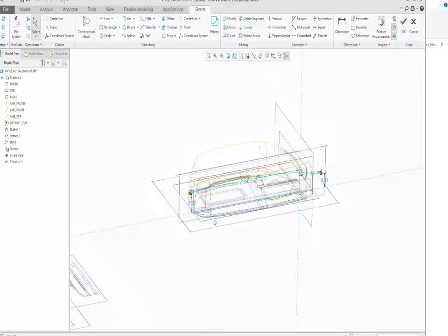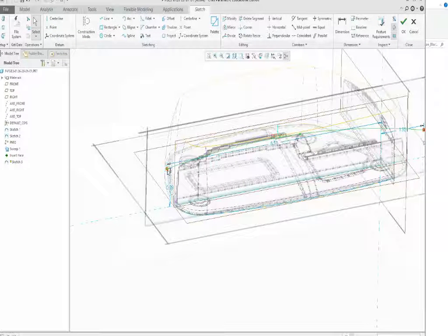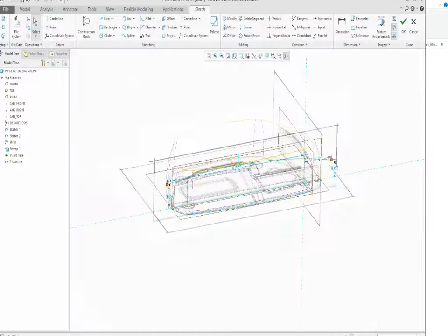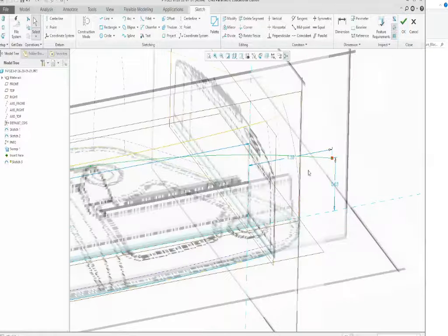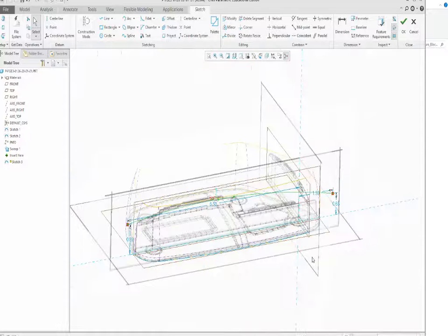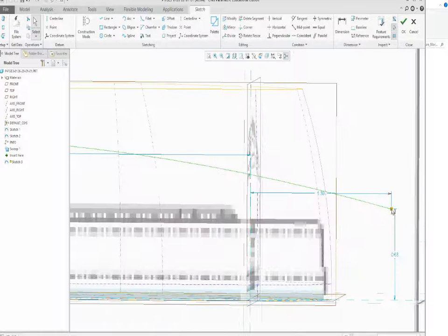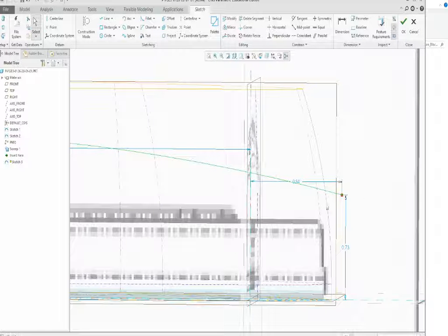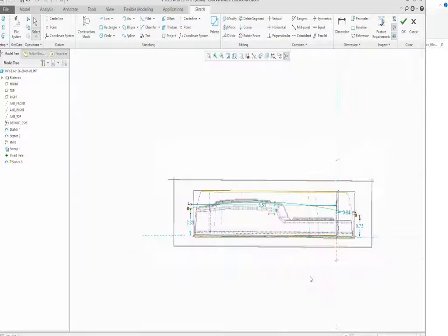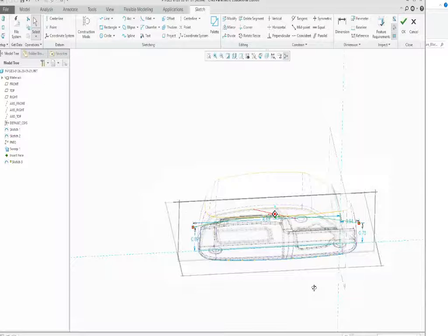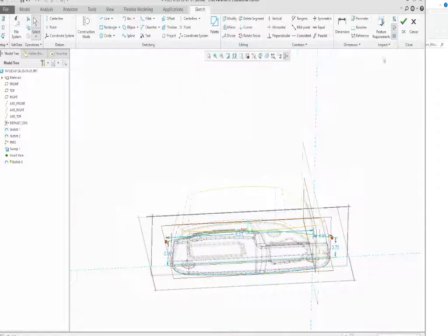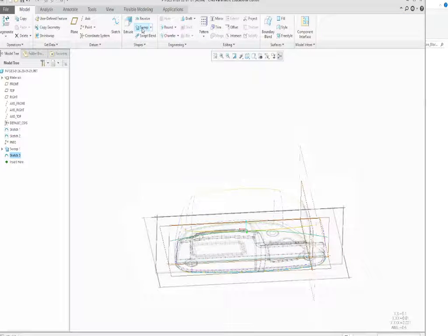Now, same scenario. On trying to do this, we want our sweep operation to happen right here at the end of the profile. And then we've got to try to pick up this other profile on the design. When we're a little bit low past this profile like this, it can be harder. Your orientation might be sweeping up a little bit on the design. So if you wish, you can pull inward and get this thing real close to the wall to see your profile. Now, once you've got that, just don't go inside the wall. Hit check, then we can go with the other sweep.